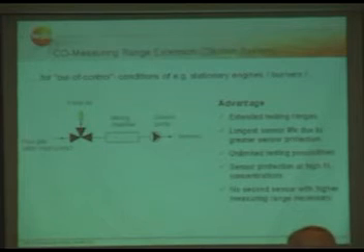That means, for example, if you have 1,000 ppm CO and you choose 20 times dilution, the sensor won't see more than 50 ppm. And this helps to protect the sensor at high concentrations. 1,000 ppm is not much, but if we are talking about 10,000 ppm or 20,000 ppm, what we recommend is to measure not that long, within a few minutes, and then to rinse with fresh air to protect the sensor.